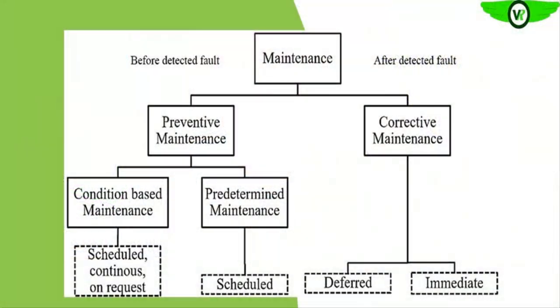All of them put together always fall into two broad categories, which is what you are seeing on the screen. One is preventive maintenance, and the other is corrective maintenance. So we'll see the various maintenance programs that fall into these two categories. The name preventive maintenance means maintenance that is deployed to prevent failure. Are we getting it? So any kind of maintenance program that you have in place in your facility to prevent the equipment, the electrical asset, from failing, that is preventive maintenance.